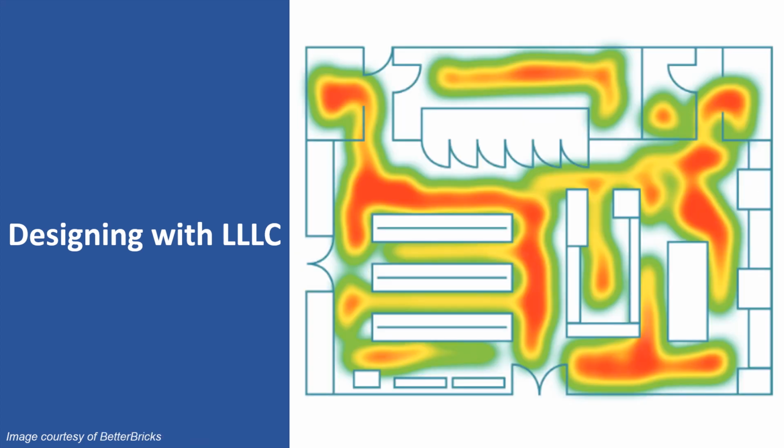As a control solution, a luminaire-level lighting control system can simplify energy code compliance, particularly in complex spaces such as open offices. If that is the sole goal, a clever luminaire-level lighting control system may be appropriate and achieved with relative ease. With smart systems, the luminaire-level lighting control may be programmable from a central point with data collection.